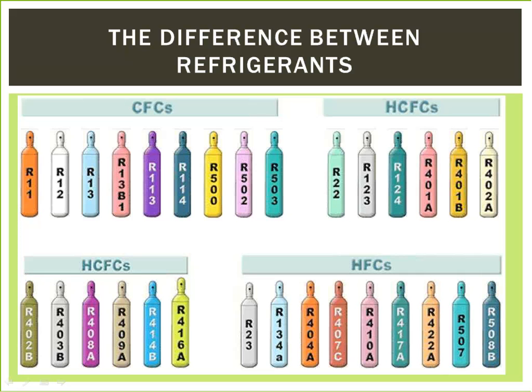Retrofitting and servicing R22 units require the use of one of the many R22 retrofit refrigerants available. On a very basic practical level, R22 and R410A have three obvious differences: operating conditions, particularly system pressures, lubricating oil requirements, and charging procedures.